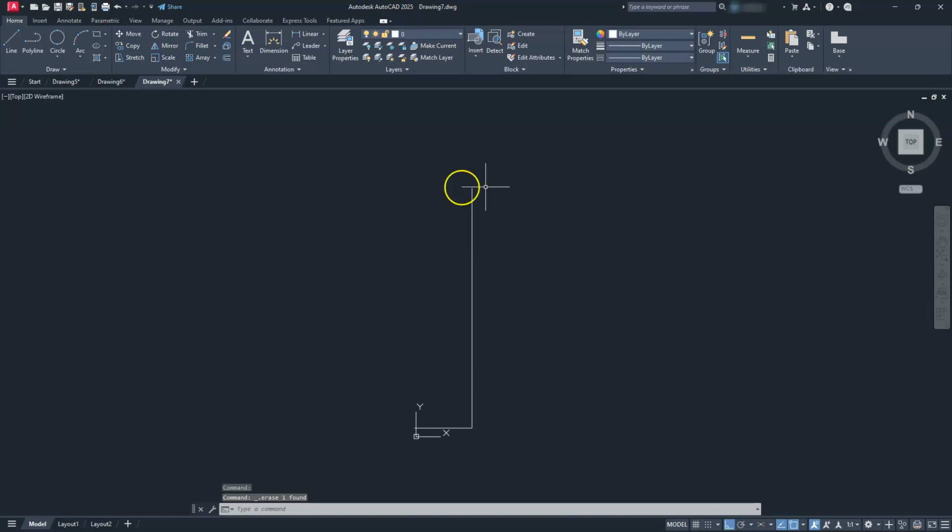And just because if I want to be a little bit difficult, I can also use the rotate command, right? So we saw me use this one once again when I created that 2D drawing there, but I can go to rotate. I can select this line here, hit enter, go from this midpoint, use the copy, and then tell it 180, right? All of those should work, right?